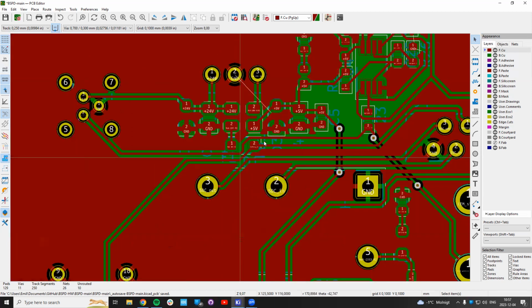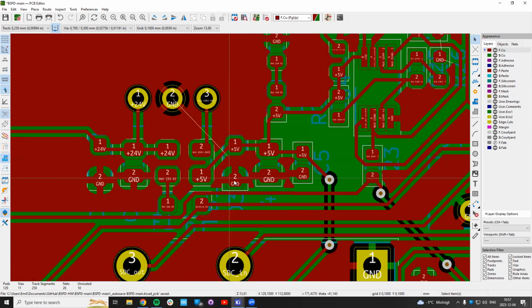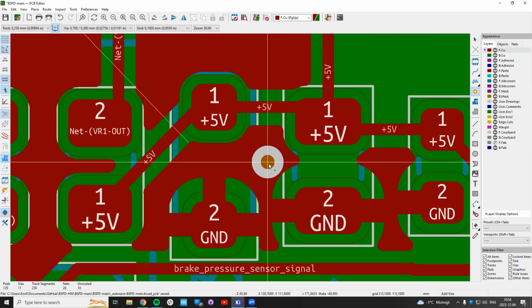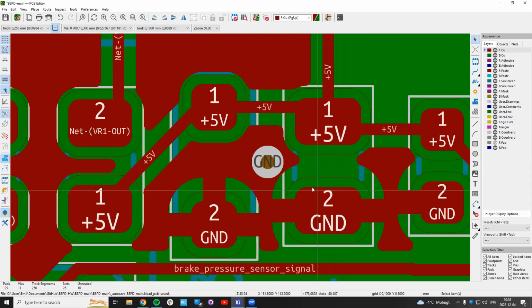And how can this copper? So think of it as just copper. This red part here is copper. How can this copper be connected to this one? It's impossible. We have traces that are surrounding it. So what can we do? Well, if we could manage to have the current go through the bottom layer here, then suddenly we could have a connection. So we add a via, place it here in the middle, boom, this is ground.